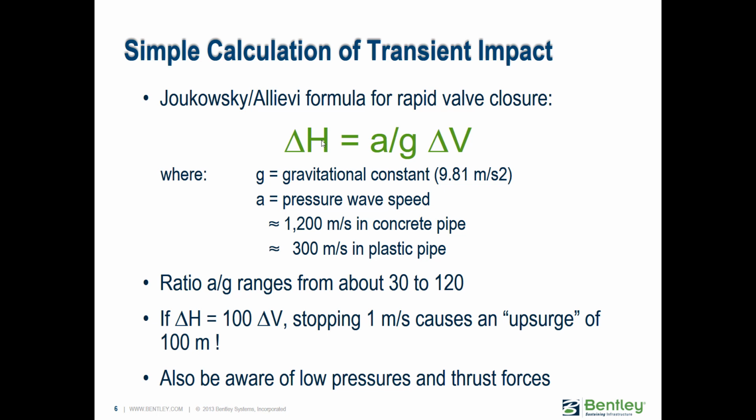But if it is, then instead of just saying we have to do something and provide some protection, what you really want to do is go ahead and actually do a full transient simulation in Hammer, because as I said, there can be other complications and other interesting things that contribute and could even make things worse than that simple rule of thumb.